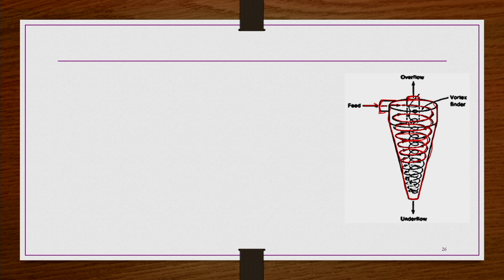And then in this process, the particles in this feed are hit on the walls of this container, the cyclone separator, and then settle at the bottom and are taken as a kind of underflow, right. So, once this feed reaches the bottom like this, almost clear liquid generates a kind of secondary vortex which moves upward through the center of this larger vortex like this, and then moves out as an overflow from here.